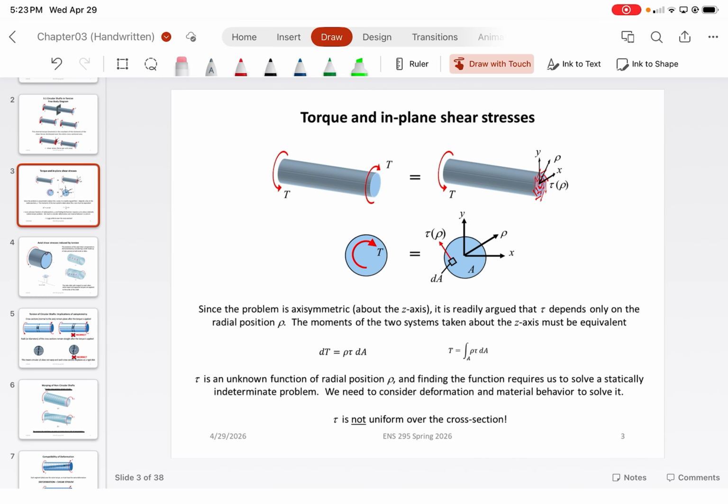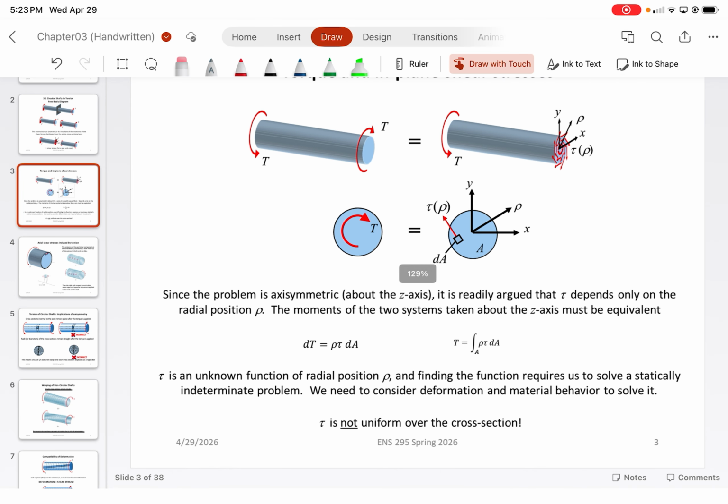All right. Now, when we analyze the torque, we first need to break it down into looking at a particular section, all right? This is ultimately how we determine the stresses. If you guys recall, when we were finding the stresses on an axially loaded member, it was just the summation of all of the individual forces for some cross-sectional area dA, which is some infinitely small area. And we basically just added all of the stresses to the equivalent areas.